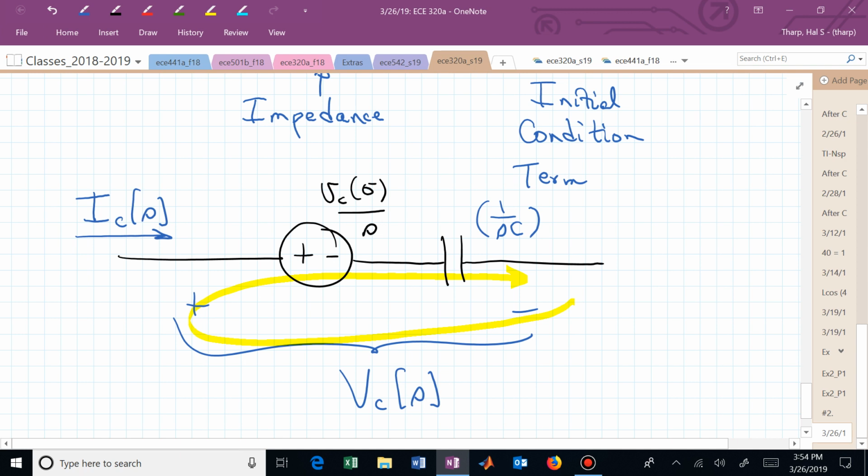So what happens when you zero out a voltage source? It becomes a short, doesn't it? It's a wire. So now if that was a short, you wouldn't have that voltage source, but you wouldn't open your circuit up.